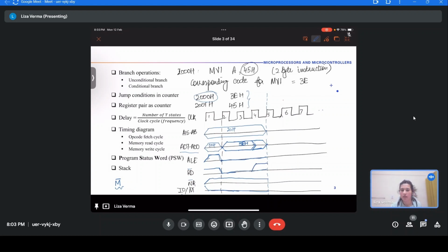The only thing that was to be done was to get the opcode to the data bus. After T3, the opcode is on the data bus going to the decoder, and during T4 the opcode is being decoded. So yes, it can go high. Thank you.